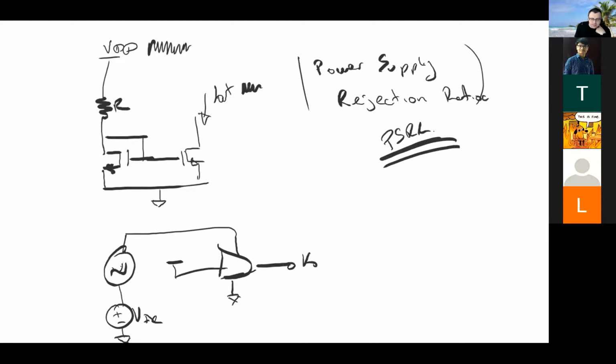We're going to simulate this for amplifiers and bigger structures in a few weeks, but the concept already applies right here. It's pretty obvious that if this power supply was moving around, it's essentially modulating the current flowing through this node, which this transistor is then mirroring and copying over to here. So we see this relationship in the output current when we're changing VDD. We spent a lot of the lecture looking at ways to make better currents that were less dependent on the supply.